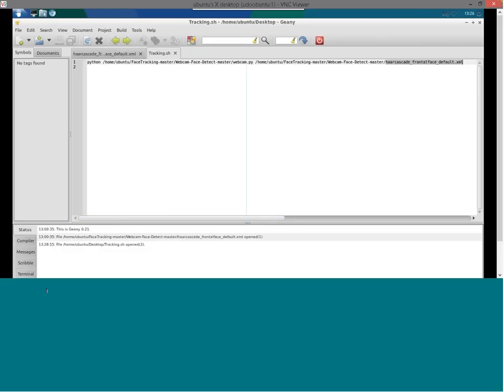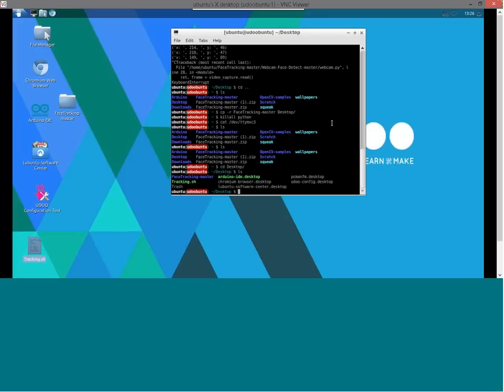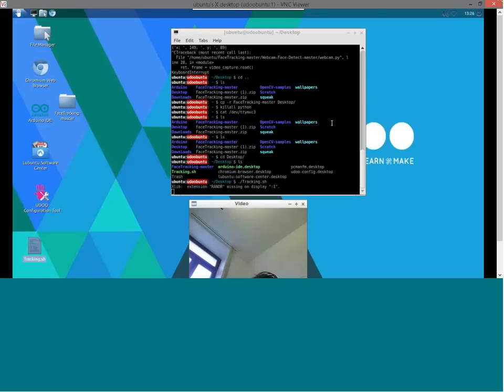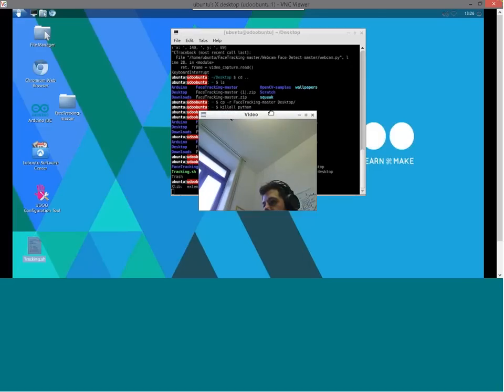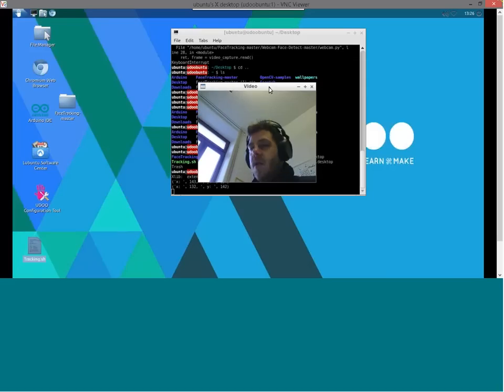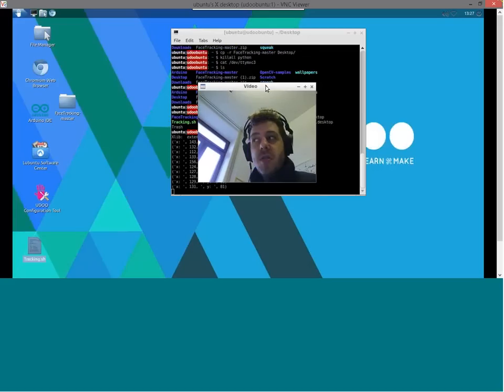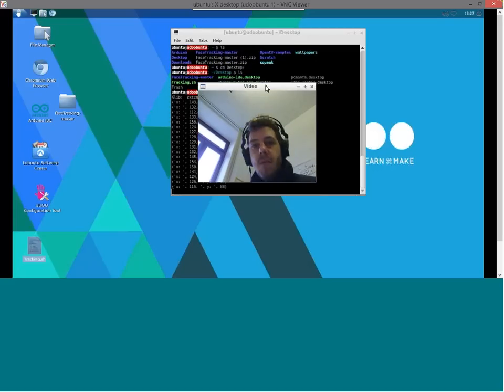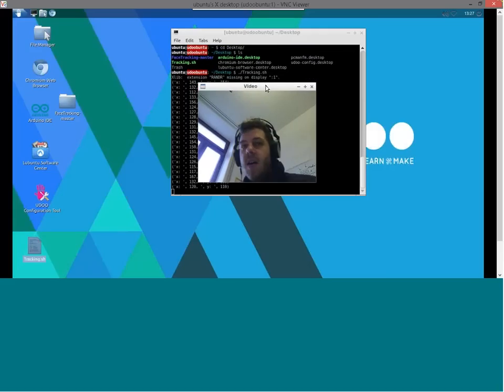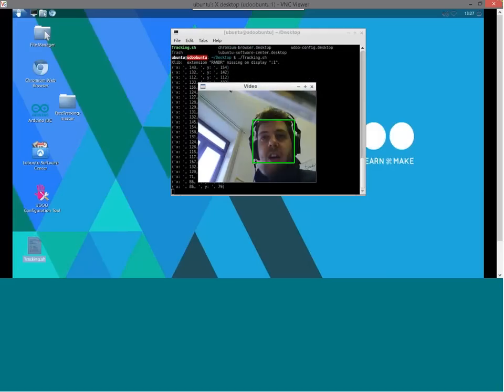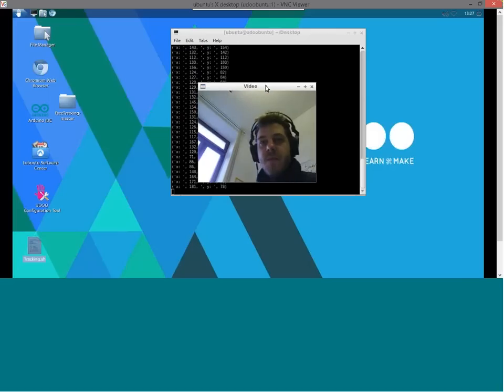So if I launch tracking.sh, now you should see the video capture, and it is getting my face in real time. You see that the camera is moving. Of course, the lighting conditions are not ideal now, but it is getting my face and it is moving accordingly, thanks to the communication between Arduino and Python.